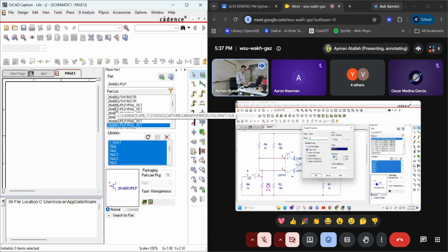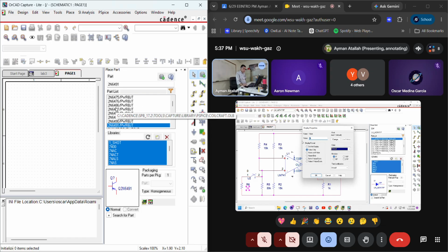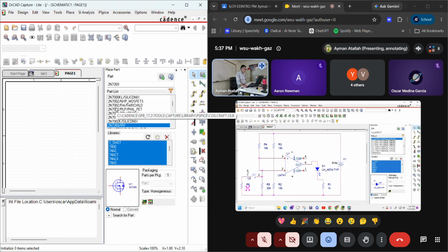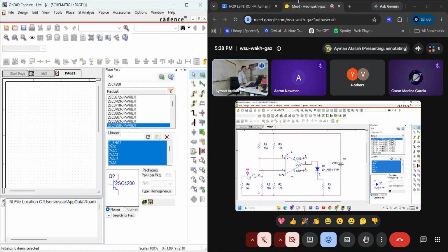This resistance is 30K. This is 15K. This one is 5K. And this will close after 2 seconds. It's important to remember this, to make it close after 2 seconds. Because from the beginning of the simulation until 2 seconds, the resistance here is 30K. After 2 seconds, another resistance will be in parallel with this, so it will reduce the voltage here. Okay. So I forgot to connect this source here, this to this, and this to ground.